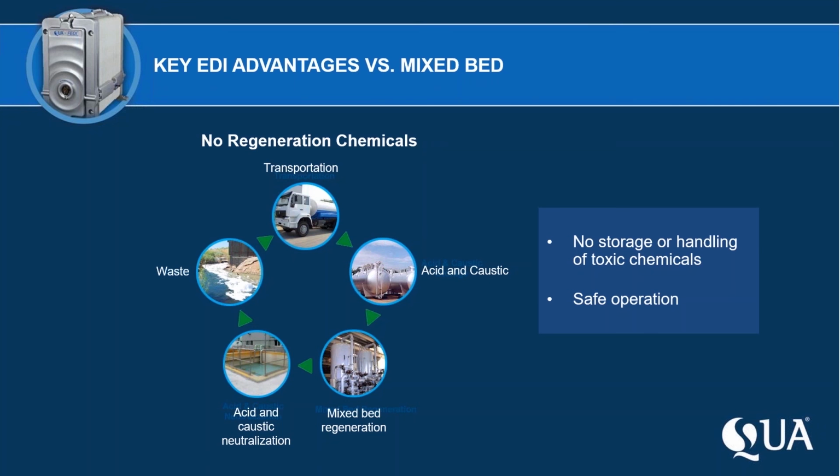You don't need neutralization of the waste stream. You don't need any type of transportation of chemicals or waste off the site. Most EDI, I know when it first came out, the price of EDI has dropped considerably over the past 20 years, where most of the payoff for an EDI, comparing it to a mixed bed, is well within one annual period. So if you're considering a mixed bed technology or a service DI type, certainly over a 12-month period, EDI is extremely cost competitive these days.